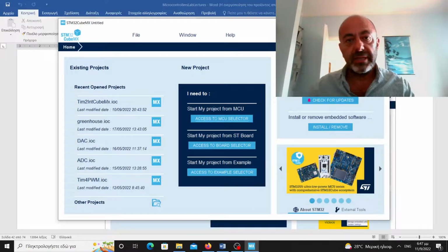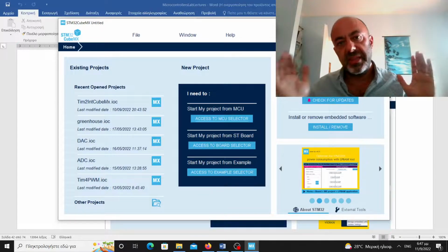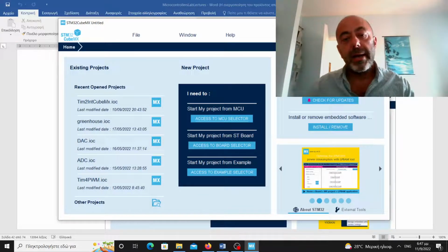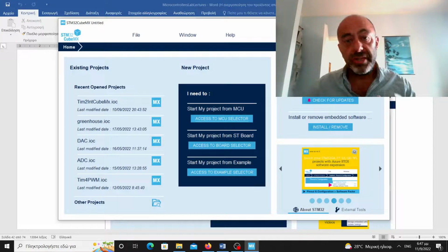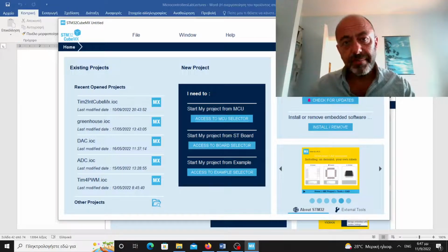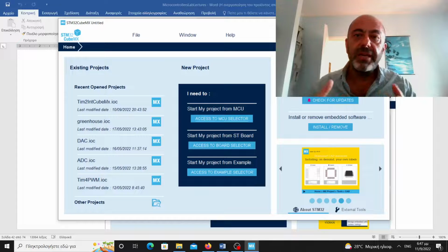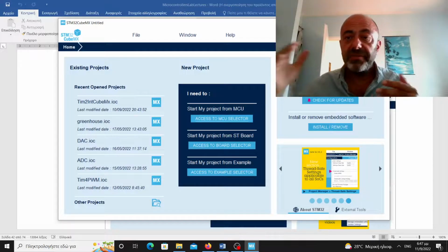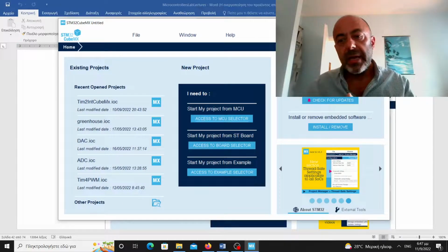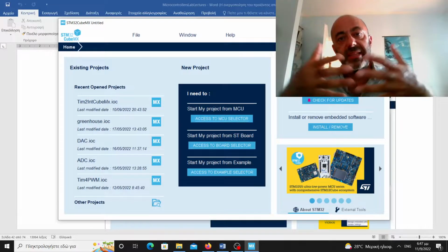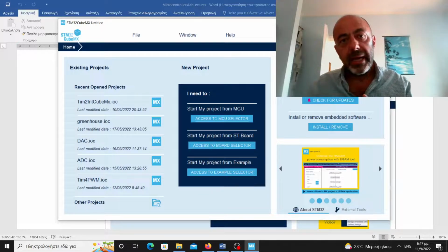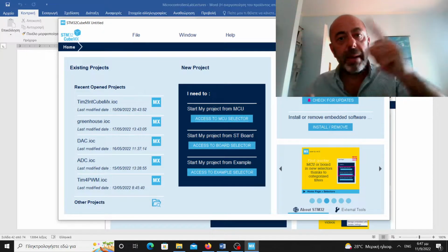So, for example, you can define that on a specific pin that is related to channel, let's say 3, of a timer counter, we will set the output pin to be toggled after 1000 pulses. So in this way, during the initialization phase of a timer, we define what we would like to happen on specific output pins after a period of time. There are multiple output pins that can be used, and there are multiple output channels that can be related, each channel to each pin. So this means that we can schedule different things to happen on different output pins.